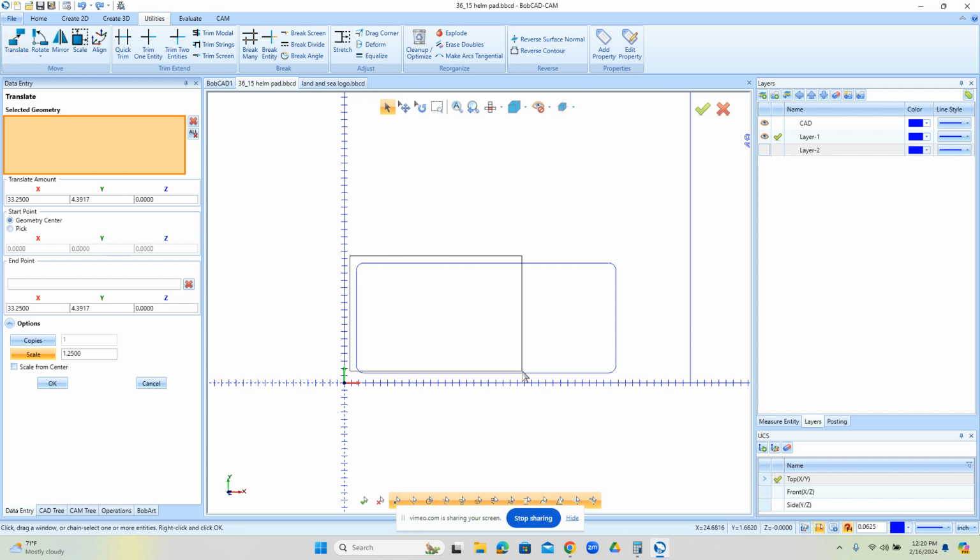Okay, we're going to window pick this. So move your mouse above and to the left of it, drag a window down below and to the right, and then now you're able to move it. Okay, so I had a scale factor over here. You can see it remembers your previous position. So it moved it over to a position.